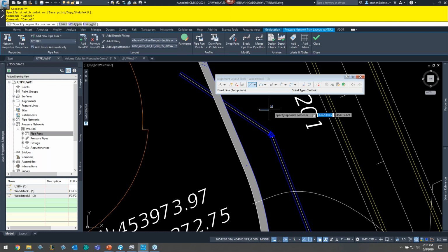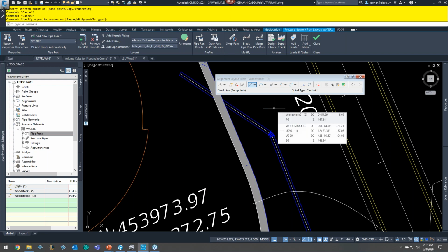So, of course, you're going to have pipe runs that last maybe miles before you even need a fitting. I shouldn't say miles, but a few thousand feet. But it can go along an alignment, and it can be curved as long as it doesn't exceed the deflection angle per the pipe standard, the material and everything that you have. That's fine, but you don't need a fitting.